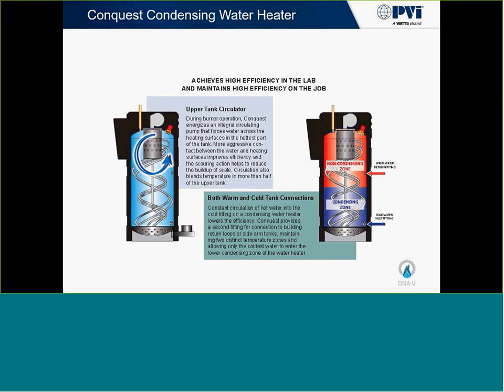With us having a mid-tank return fitting, what we're doing is we're bringing that return water into the non-condensing zone of the heater. That's important because whatever water is used in that system, we're introducing as cold a water as possible inside that tank into the condensing zone. So that allows us to maintain those much higher efficiencies at minimal flow rates, because no matter what we use in that system, we are always introducing as cold a water as possible to make sure we scrub off as much heat as possible into that water.